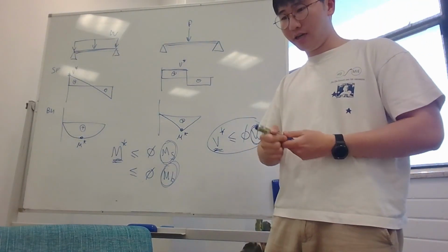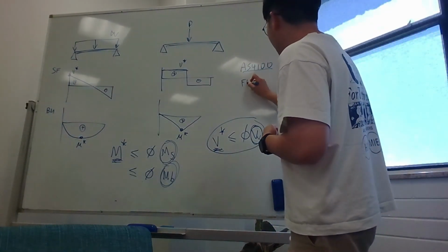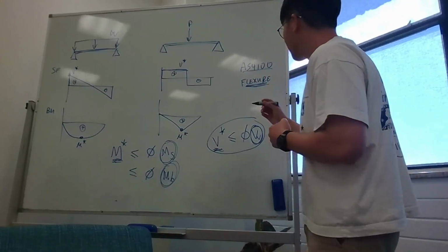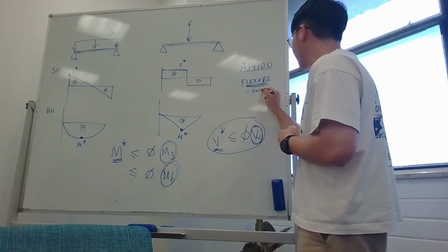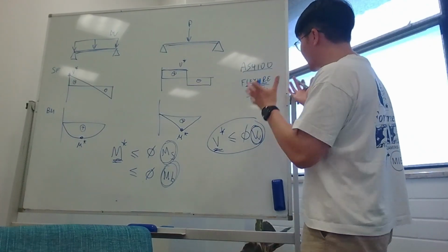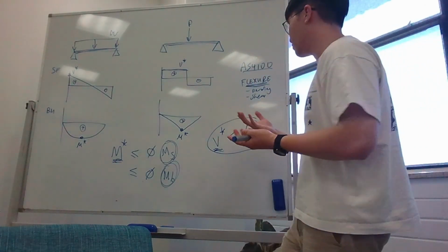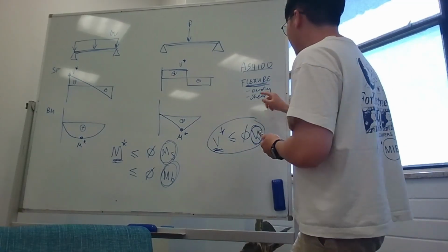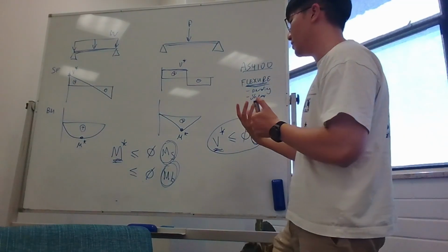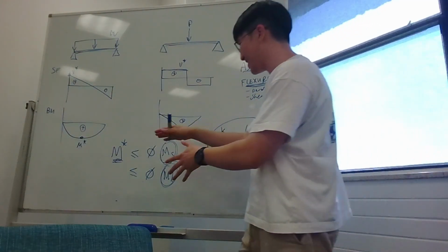If you look at AS 4100, the steel standards, under the topic of flexure, you see both bending and shear. Flexure is just the fact that your beam is taking transverse forces. Then you find the bending capacity, but directly under it is your shear capacity, because shear is heavily tied in with the concept of bending as well.